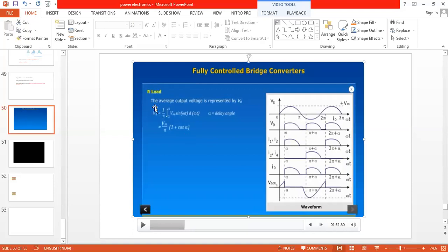Okay, right, good. Average output voltage. So what is this word called average? When we convert AC to DC, we are not going to obtain pure DC. A certain amount of AC components are also present, which are called the ripples, unwanted AC signals. So the output voltage signal we are getting is a combination of AC and DC components. The DC component in this signal is called the average, which is approximately equal to DC. So what is the formula for average voltage?